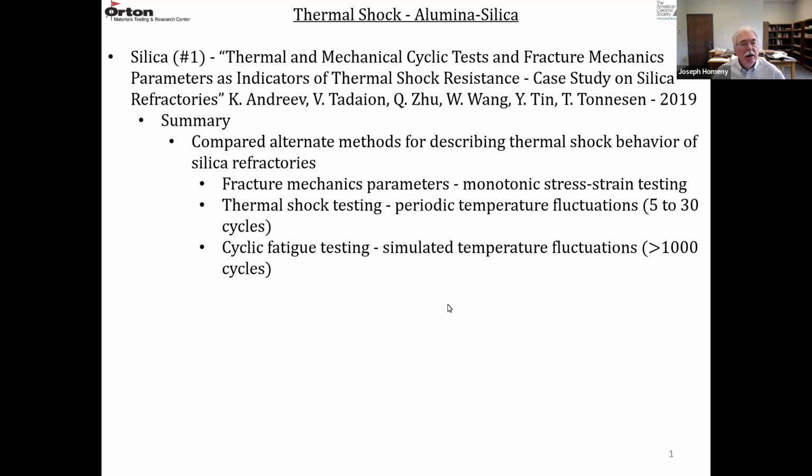Good morning. We went over the first part of this course, basically the background for thermal shock theory. We went over elastic properties, thermal expansion, thermal conductivity, fracture behavior, and then we looked at the theory that's been developed with the different R parameters over the last 40 or 50 years. And we also introduced some other parameters like J1C, the J integral, and rising R curves.